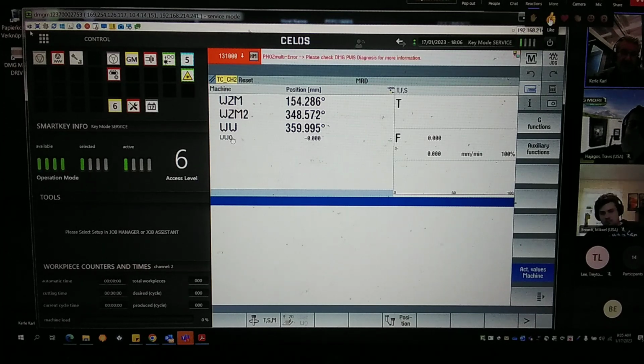Here we have to separate the 31 axes into 3 channels, okay? And every channel, depending again on the configuration, on the type of axis, has a maximum number of axes. Each channel is 10 axes. More is not possible. And 10, let's say, is the maximum in the case of auxiliary axes.